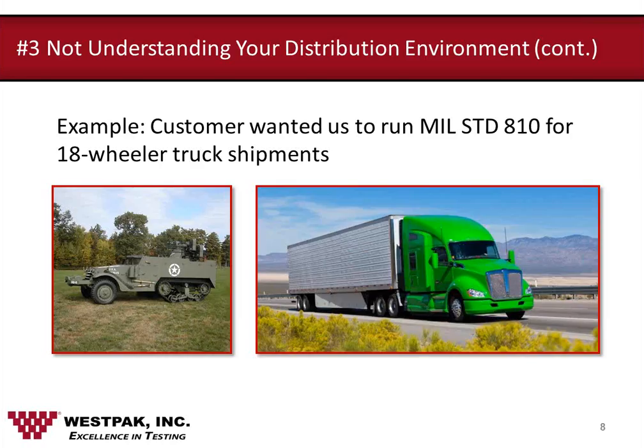If they would have done the testing per the MIL-STD-810 half-track vibration profile, they may have ended up with false failures and damage that they would have been trying to protect against that it's not going to ever see in the in-use or their current distribution environment. So there's an example of how knowing your distribution environment will help you design your package and testing around that.